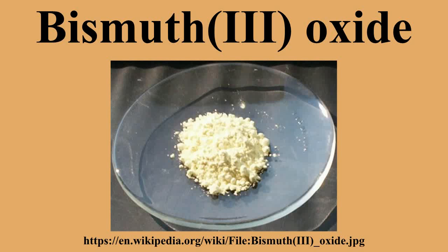Delta bismuth trioxide has a defective fluorite-type crystal structure in which 2 of the 8 oxygen sites in the unit cell are vacant. These intrinsic vacancies are highly mobile due to the high polarizability of the cation sublattice with the 6s2 lone pair electrons of Bi3+. The Bi-O bonds have covalent bond character and are therefore weaker than purely ionic bonds, so the oxygen ions can jump into vacancies more freely.